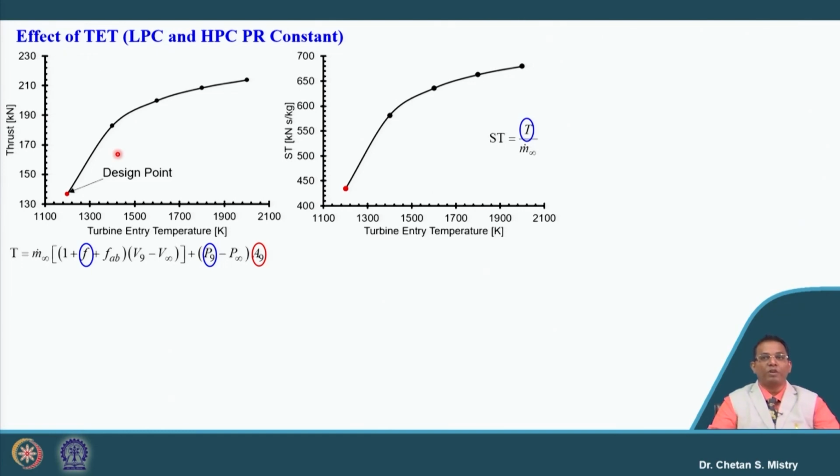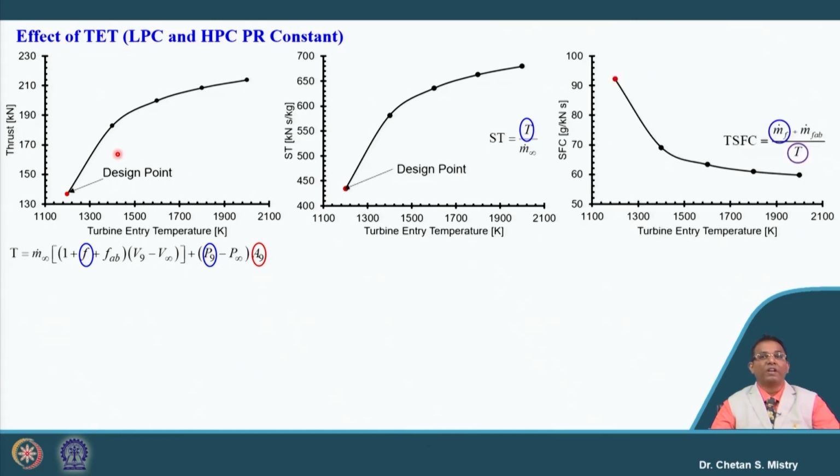Let us see how much you have understood here. Let me give you a hint. In order to raise the temperature, basically you need to add fuel. Then only you will be able to raise the temperature from 1200 Kelvin to say 1500 Kelvin or 1700 Kelvin. So, if that is the case, we can say our thrust specific fuel consumption is what will lead to decrease here.